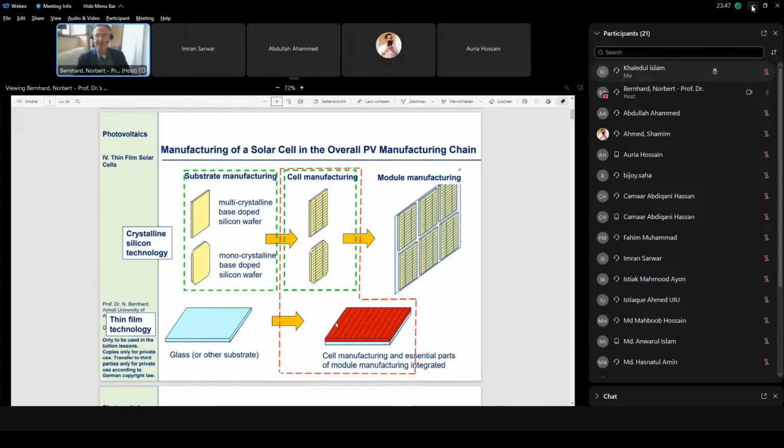And in the lower picture, in principle, we see the transition from a multicrystalline or polycrystalline material to a purely amorphous material. What is used in these tandem cells would be, in the first cell, the one to the very right, which is amorphous material, and for the second cell, something here in the middle, which is called microcrystalline. And here you also see a TEM picture, transmission electron microscopy picture, where we see, for example, a microcrystal. And here, for example, we see an amorphous region.